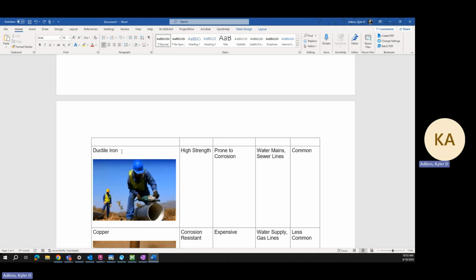It's got that high strength. It's very durable. So you'll run into the gray cast iron every now and then. But the difference between gray cast iron and ductile iron is ductile iron does have a higher strength compared to gray cast iron, making it more resistant to external loads and internal pressure. It's more flexible. Ductile, meaning flex. It allows it to withstand minor ground movement and settlement without cracking or breaking, which is nice. It's corrosion resistant. And again, it's got that durability.